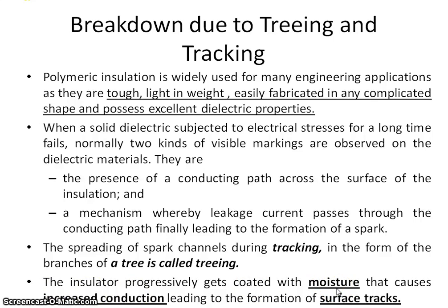Now the insulator progressively gets coated with moisture. We know that moisture is always coated on the insulating material, which causes increased conduction, leading to the formation of surface tracks. Those surface tracks are produced because of the moisture content.